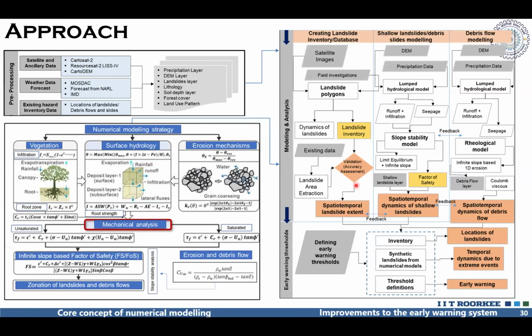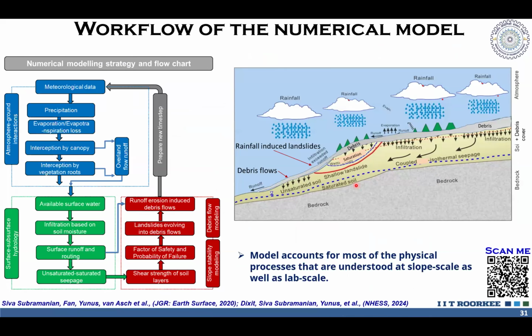So this is the approach. Since we have got confidence that, in 3-4 years time, we have got to know that this mechanism of unsaturated soil will also be applicable to an extent to a mixture of soil-rock medium, where the grain size is even larger, where the D50 is close to 20. That's the D50 we used in the flume. So we developed an approach to actually use it for the catchment scale.